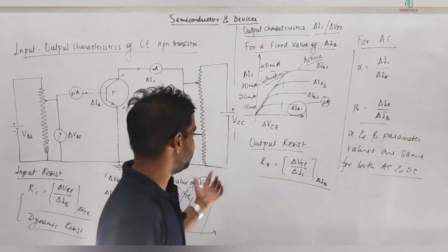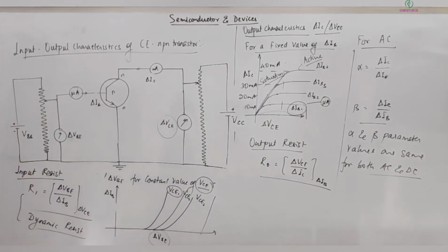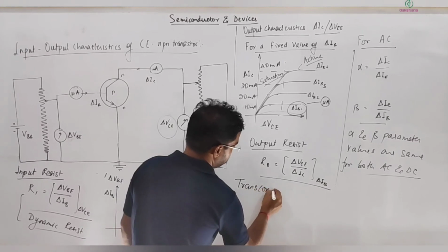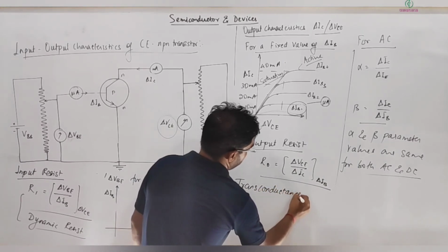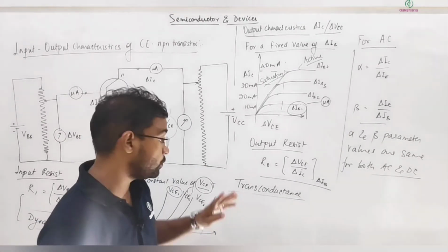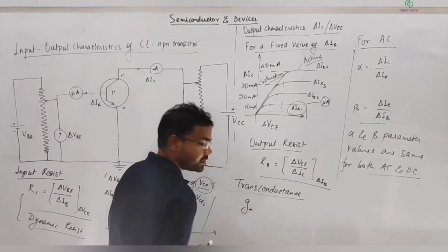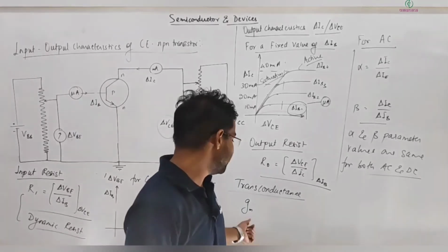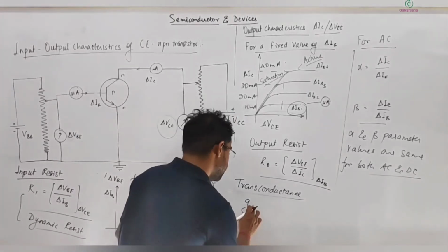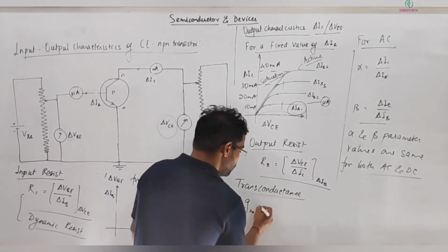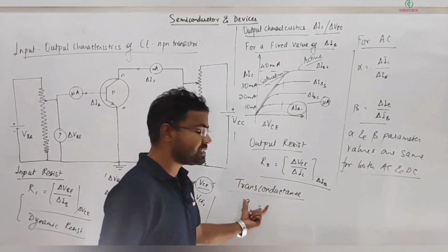So these are some points about the transistor. There is one more term that is sometimes asked, called the transconductance of the transistor. Sometimes this will be asked to you: what is the transconductance? We denote it G. Conductance is the inverse of resistance, and for conductance we use the letter G. So here we write G m, and it is not simple conductance.